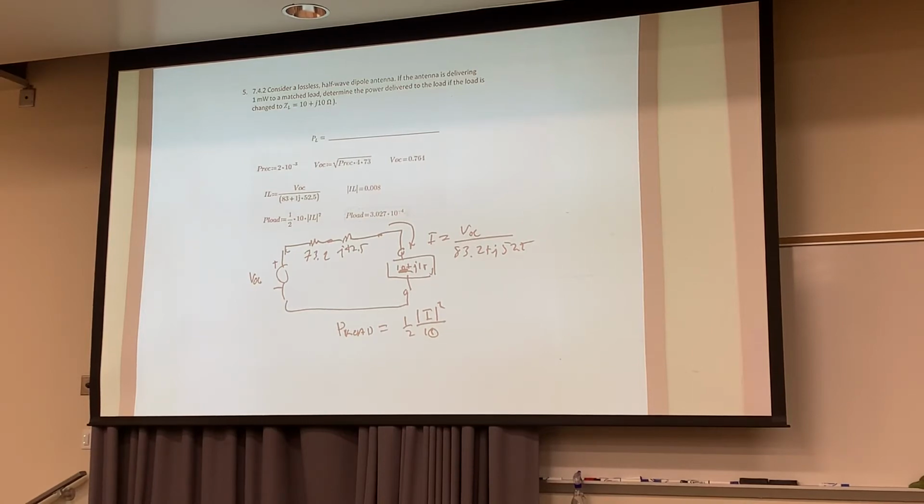And also, conducted emissions, this is another thing. If you've got something like a hair dryer, you plug it in the wall and you start drying hair, well, there's an electric motor in there, all right? That motor has sparking. The sparking and things like that literally cause a high frequency current interruption that gets propagated into the wall, at 100 kilohertz or so, maybe even higher than that. If you plug in your TV, if you've ever seen this, you know what I mean, and all of a sudden you turn the hairdryer on and you see the TV get jittery. Or you can hear it sometimes if the equipment doesn't have good filtering. You can hear it in literally the audio feed too.